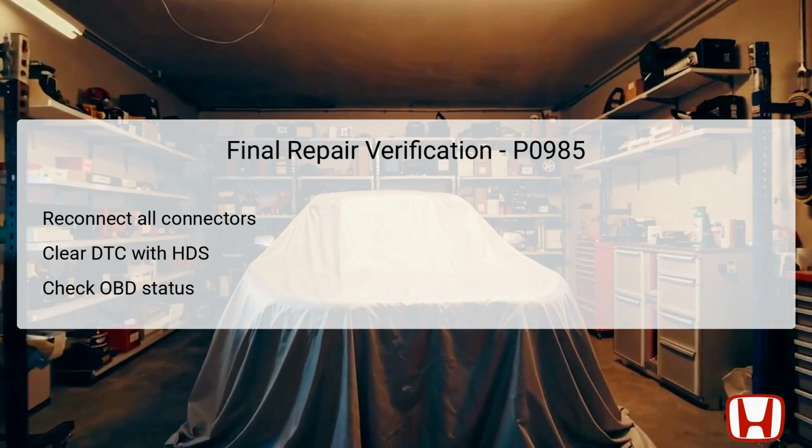Begin by reconnecting all previously disconnected connectors to restore full electrical functionality to the system. Once all connections are secure, turn the ignition switch to the on position, second stage, and proceed to clear the DTCs using the Honda Diagnostic System, HDS. This step is vital for resetting the system and allowing for an accurate assessment of the vehicle's status post-repair.